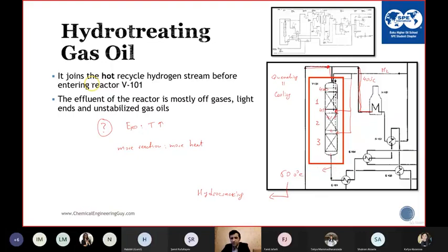Once it leaves the reactor, it goes to the pre-feed heat exchanger, where we preheat our inlet. So this is our product, and it goes like this. We use the heat from the product to heat the feed. So this is also a HEN, heat exchanger network. We have a heat exchanger network at each unit. Everywhere we have it.